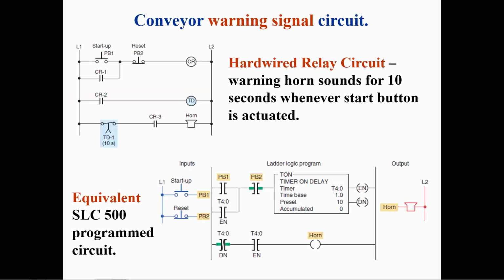Another application of a timer on delay is to sound a horn for 10 seconds after the startup push button has been pushed. In the ladder logic program, the enable bit of the timer, T4:0/EN, is used to latch in the startup push button, PB1. The AND combination of the examine if open addressed to the done bit and the examine if closed addressed to the enable bit replaces the normally closed timed open contact from the hardwired relay circuit.